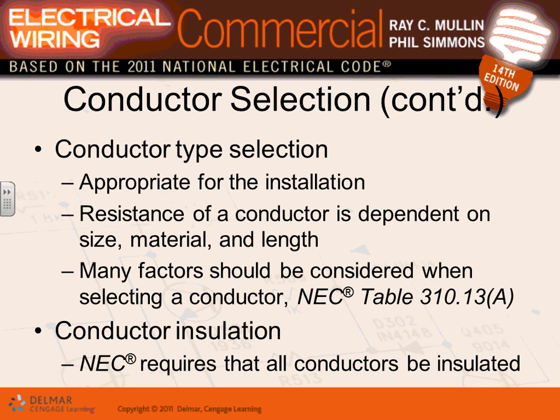How far can I take a 20 amp circuit away from this panel without exceeding the 3% or the 2%, in this case for branch circuit, of voltage drop? That's a big deal. So sometimes when you hear me telling you don't put more than 17 fixtures on a 120 volt circuit, you say, are you kidding me? But keep in mind, when you don't want to put more than 17 or 18 fixtures on one circuit, you're taking into consideration the voltage drop, grouping them together, and continuous load.